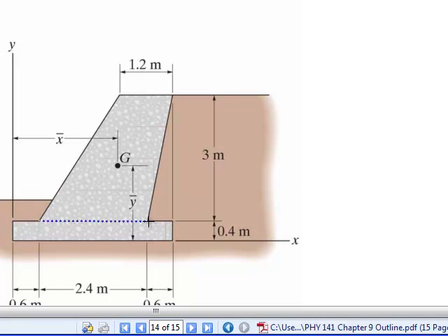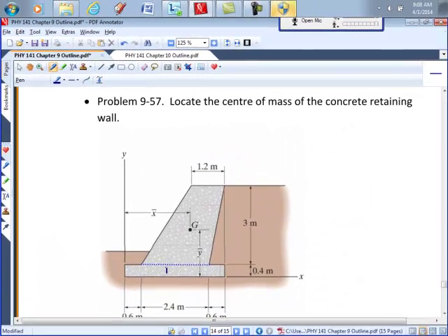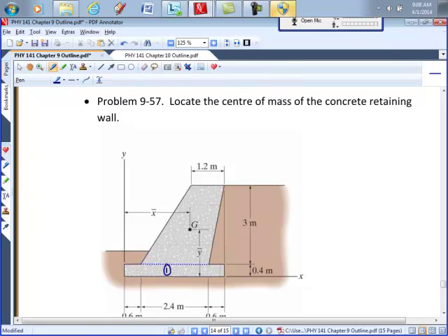Okay, so definitely agree on that one. We'll cut off the bottom rectangle. That'll be section 1. Now for finding the centroids, yes, I could make this into 2 triangles, but if I draw this line here obliquely, then the location of the centroid in relation to the x and y axes is not going to be easy to find. So I'd be better to cut the top bit into 3.